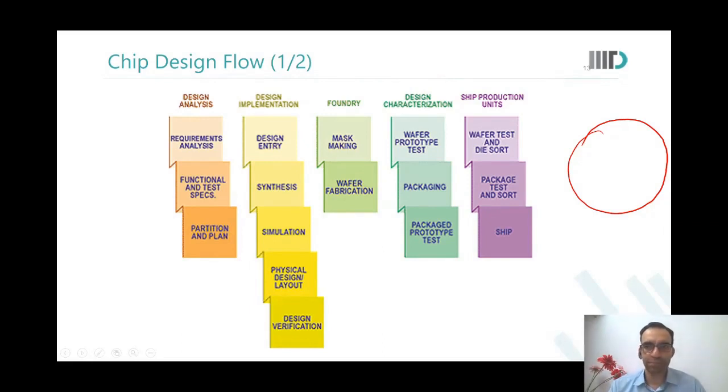So would you say that the fault was in the test specifications, that it did not test all the cases? It could be anywhere. It could be in their understanding. It could be in the design implementation. They had designed it such that they put in more memory and said this will lead to better performance. But due to more memory, the wire lengths increased, let us say, and delays increased.